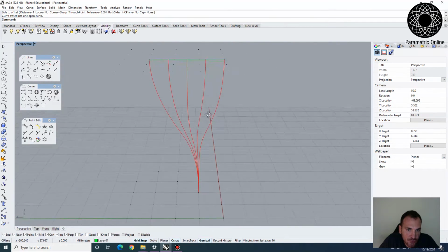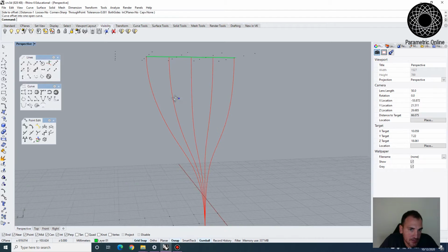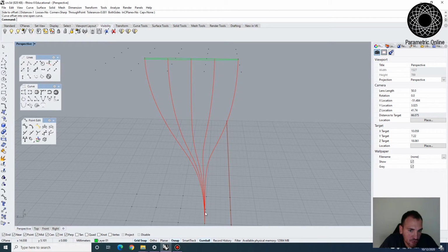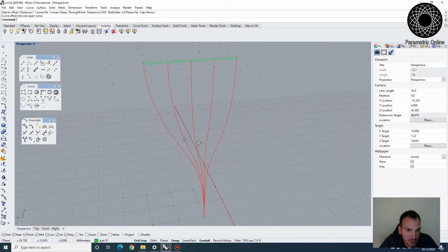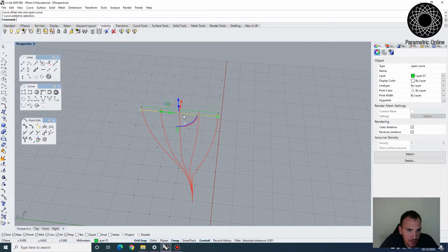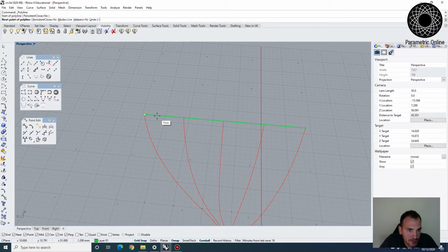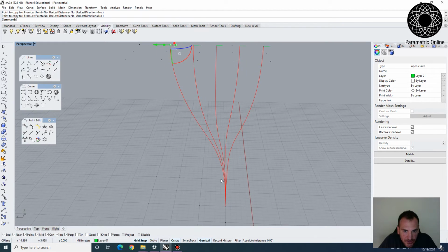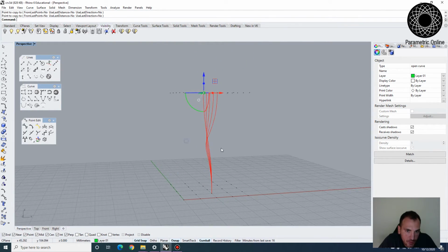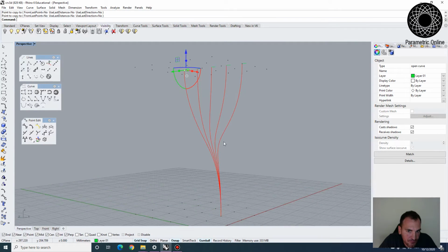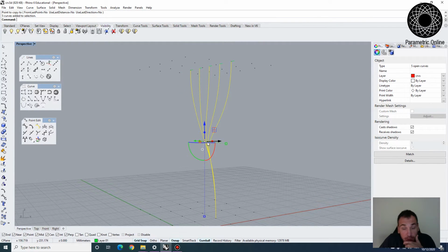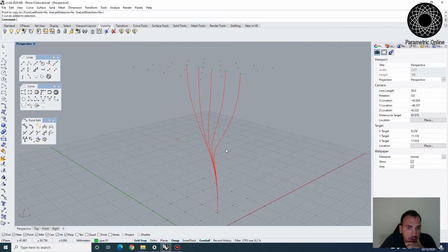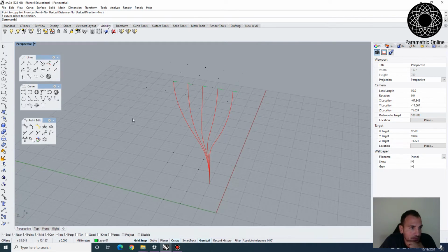Now we can actually control the sweep in the midline as well. So imagine maybe you want to have them go up vertically but then twist. So you might want to control, let's say, actually let's make them facing this way. So maybe we do, these will be the profiles on top for each of these. But somewhere here, we want them to actually face this way. And one way of doing that would be to kind of contour this curve and kind of define another profile there.